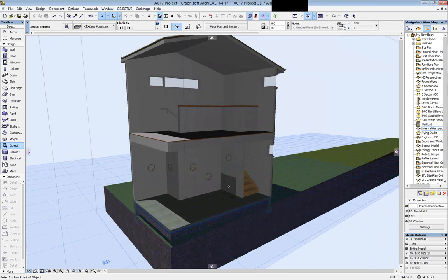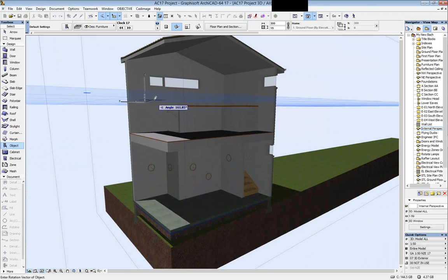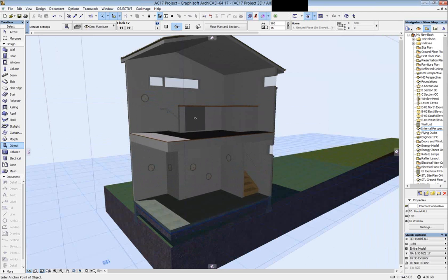Now if we were to do this in version 16, we would go into the object tool, we would set the home story, we would set the elevation, and then we would place it. But wherever I'm clicking on the screen is where it's placing that clock. I can also click upstairs. Now the cool thing about placing it upstairs is it's changed its home story to upstairs. So if these two clocks I've placed upstairs were set to display on home story only, of course they won't show downstairs. They'll only show upstairs.